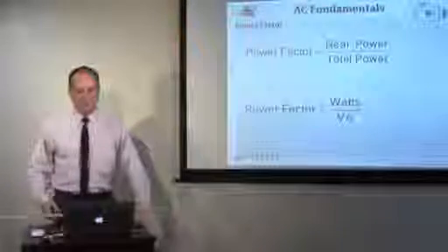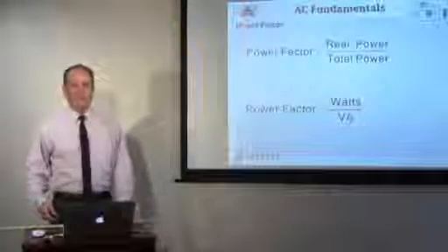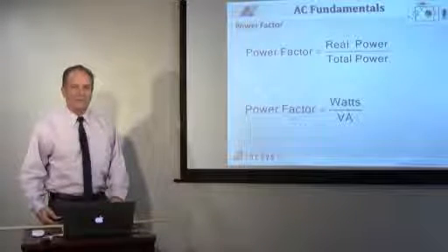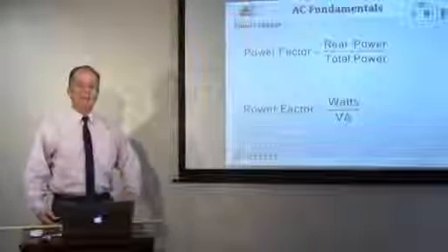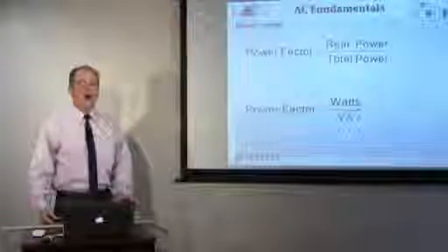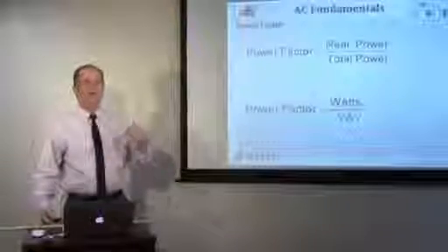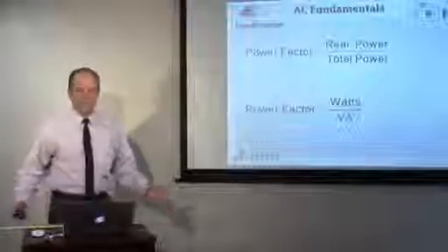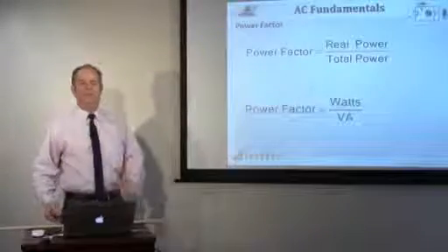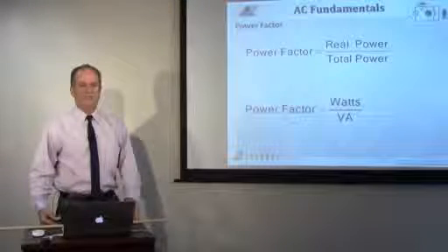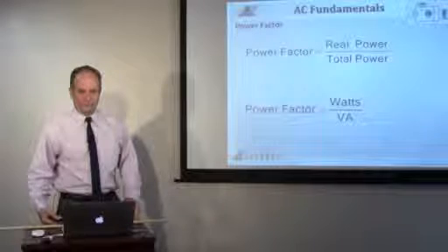And that's just a term used. It's very, very commonly used, power factor, because you want the power factor to be unity. You want all the power being consumed to be watts, or the power generated and transmitted to be watts. So power factor is an important efficiency determination in AC power systems.